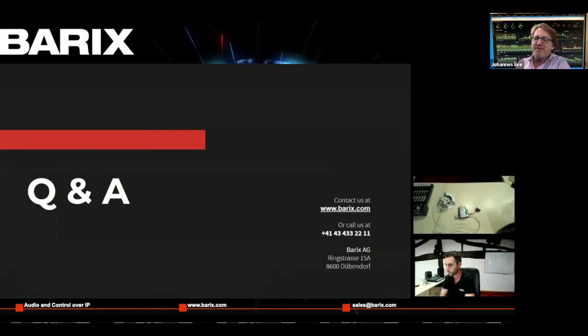You may have noticed that most of the Barionet products don't have a Modbus interface anymore, but to the rescue comes something like a $5 stick, plugs into USB, gives you RS-485. And we have Lua examples on how to read registers and write registers into Modbus devices. This is easy to do, and you can use that with IO12, with X8, R6, and that other stuff, but also, of course, with these nice energy sensors.